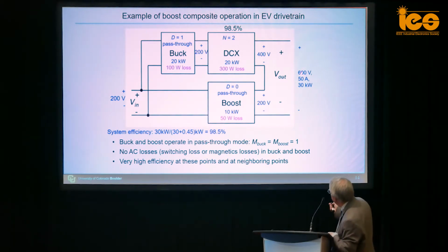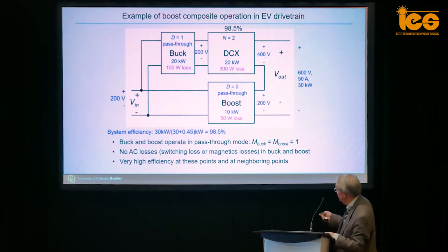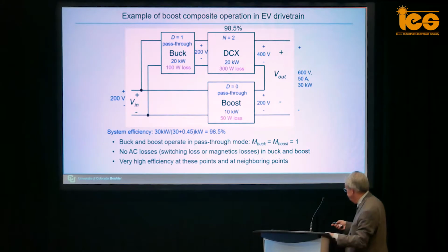If you want to raise the voltage more, you increase the duty cycle of the boost to boost its output voltage some. If you want to lower the voltage from this point, you can lower the duty cycle of the buck to reduce the voltage here. And so we can do switching that is still at very high efficiency with low indirect power to control the voltage.